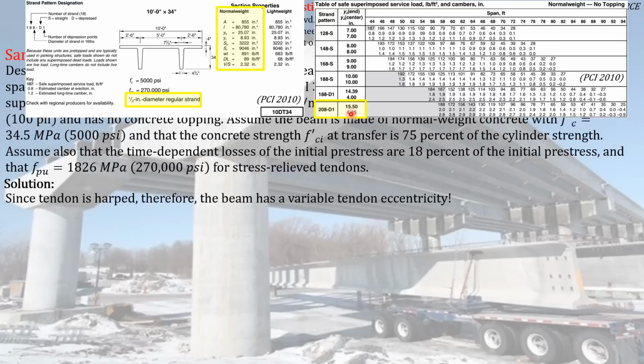So you have to take note that the distances that you are seeing here, the distances at the end and the center of the pre-stressing reinforcement, are referred to the bottom of the section. This means that the pre-stressing reinforcement at the end of the concrete beam that we are designing is 15.5 inches from the bottom of the section at the end point.